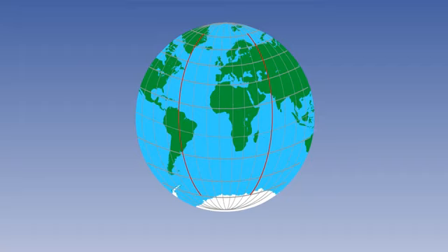Longitude is slightly more complicated, because 1 minute of change of longitude is 1 nautical mile only at the equator. You can see that the distance on the Earth at latitude B, between the same change of longitude, is less than it is at latitude A, the equator. This east-west distance on the Earth is called departure, and is measured in nautical miles east or west.